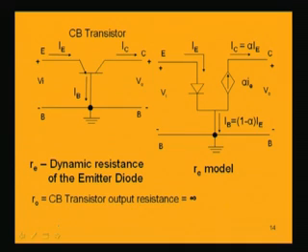First of all, let us take for example a common base transistor. If we take a common base transistor, and consider first of all a PNP transistor, this is a PNP transistor. So, in the light of the two-port network which we have just seen, this is the input port, emitter and base, and this collector and base port is the output port. Now, the transistor has input current IE, and collector current IC is the output current, and this is the base current. This is a common base transistor.